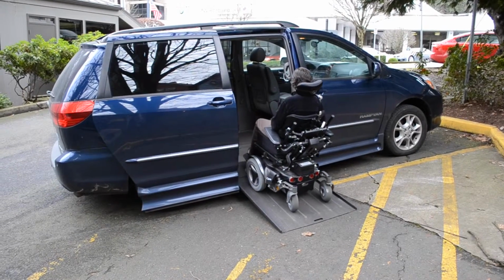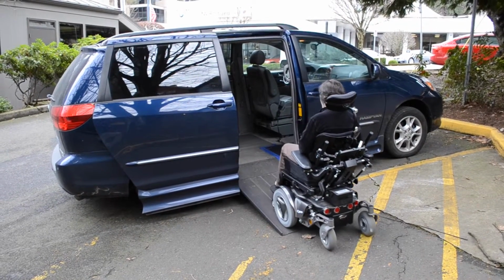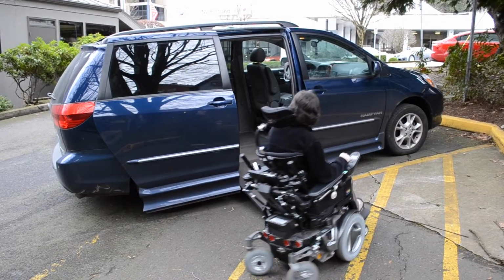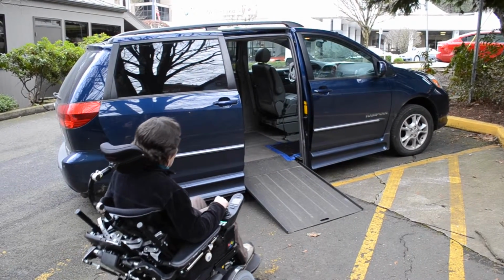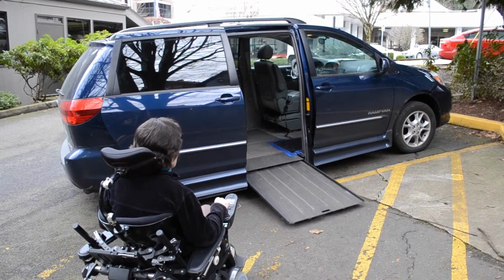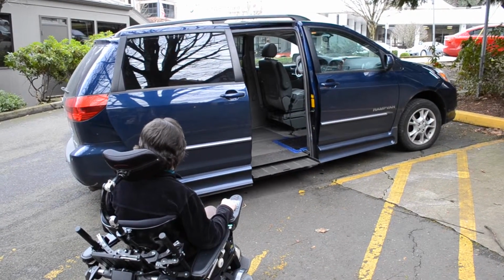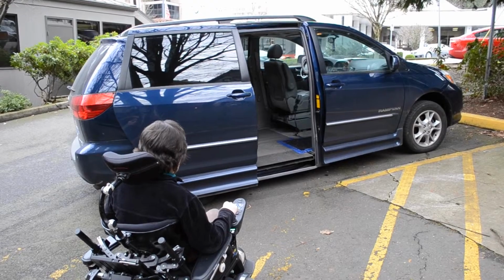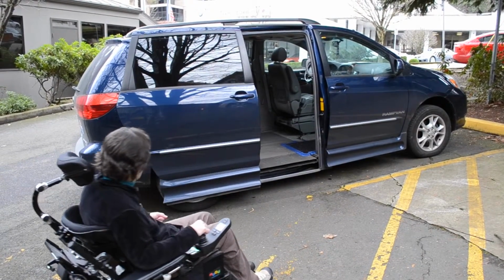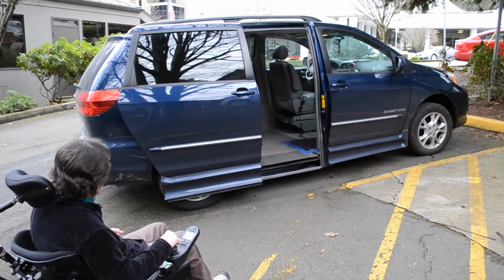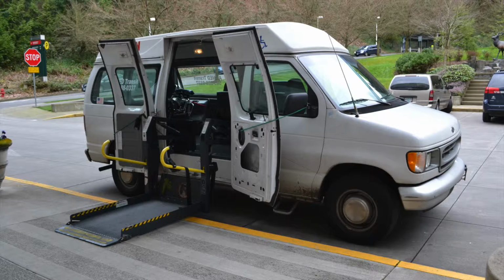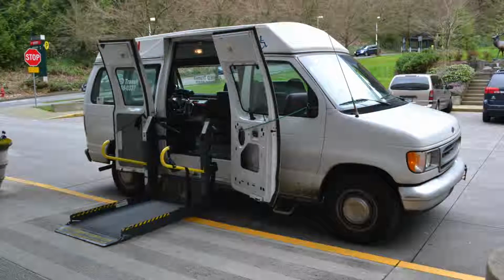Good. The grade and cross slope are critical when choosing the accessible parking spaces. In this case, Georgina's van door will not close because of the steep grade of the parking space. Severe grades and cross slopes can also result in runaway manual wheelchairs. Passenger drop-off areas need to be close to the entrance without risking passenger safety in accessing the facility.